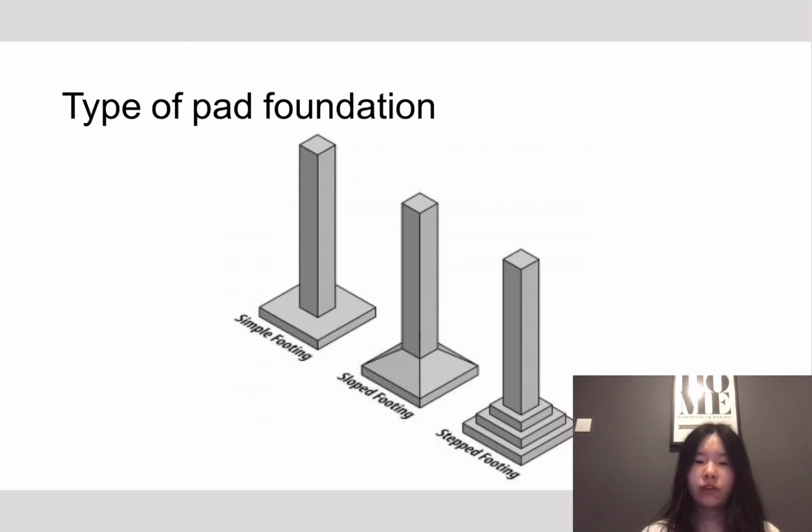Third, slope foundation. Slope foundations are trapezoidal footings. They are designed and constructed with great care to see that the top slope of 45 degrees is maintained from all sides. Sometimes an isolated footing is stepped or sloped in order to meet the requirement of foundation bearing capacity. The bottom of the foundation is made wider than the wall and widened step by step.